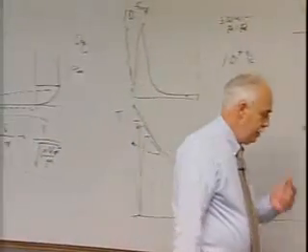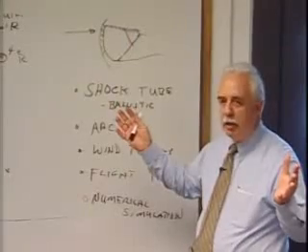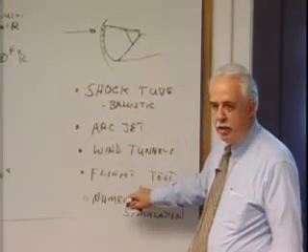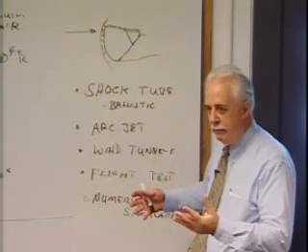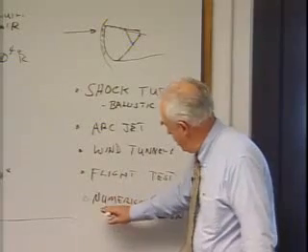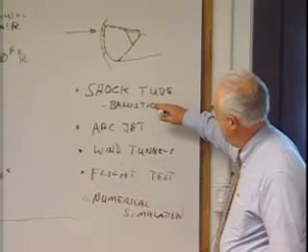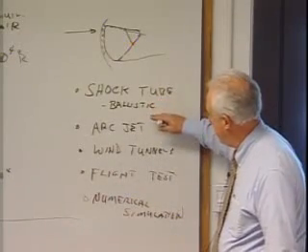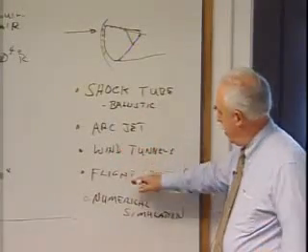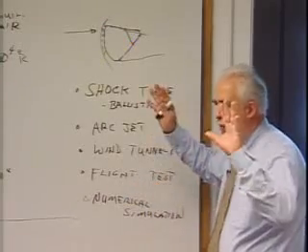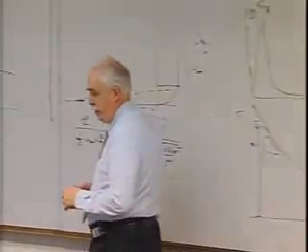That's outstanding, because now if I say I've got a program, I can tell you what the heating is, I can tell you all about the aerodynamics, I can tell you everything. Good. Run it on a wind tunnel test and show me that. I'll take the data, you run it on a wind tunnel test, and we'll see if we agree. So you've got a validation of numerical simulation in terms of the geometry in wind tunnel, in terms of the chemistry in shock tubes or ballistic facilities for that matter, and certainly in terms of flight test. And you've got shuttle data and a lot of code validation for that shuttle data. Now this is just from the heating standpoint. I haven't talked very much yet about the thermal protection system or the structure and the rest of the things.